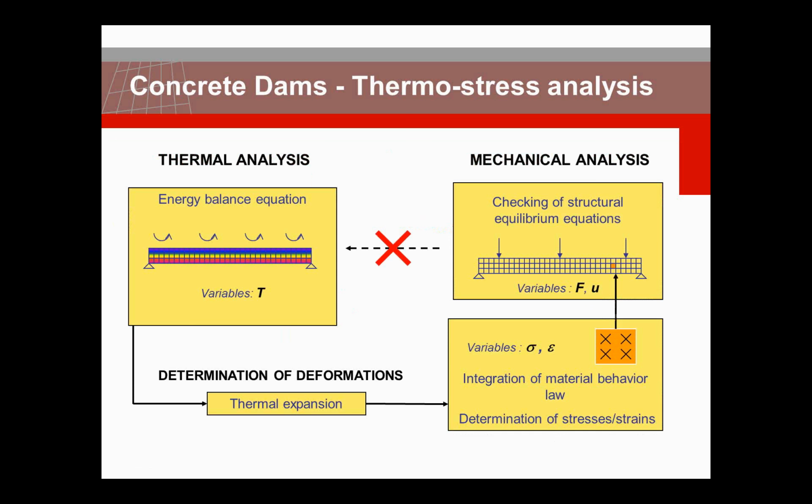So how to deal with such conditions in a finite element analysis? In fact, we need to consider 2 physical phenomena. First is the heat transfer, in which we need to look into energy balance of the system. We calculate the temperature field in the dam and then apply that as a loading condition, a boundary condition to the dam structure.